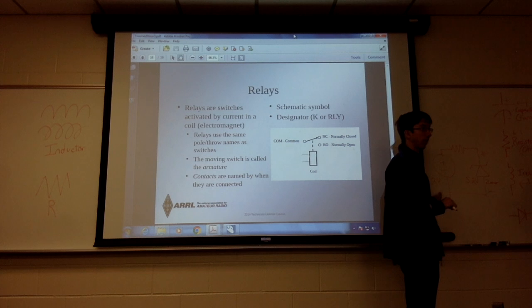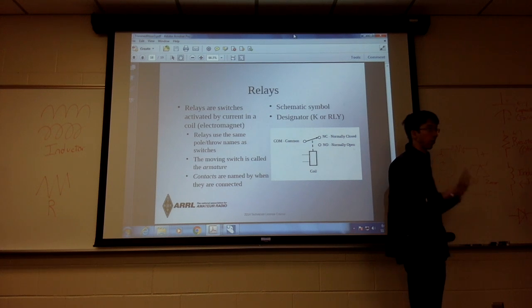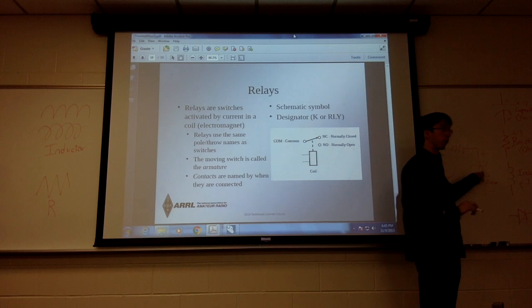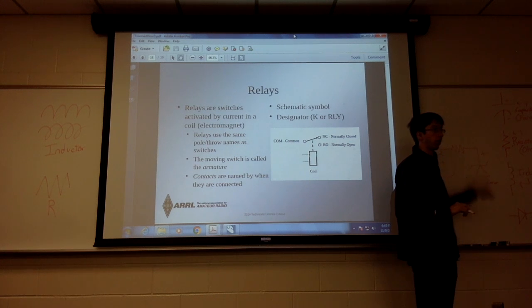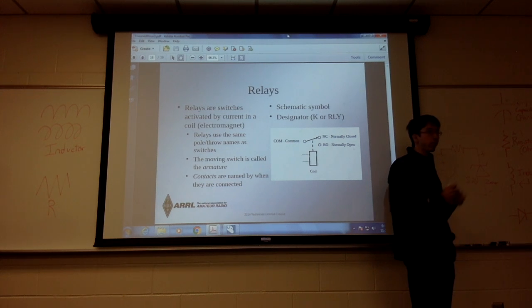If this is 1,000 volts, we'll kill it by other means. As long as this is greater than 5.2 volts, we end up with 5.2 volts across our Zener. That's why it's useful for voltage regulation, because it doesn't matter if that's 12 or 14 or 15 or whatever; so long as it's greater than 5.2, we'll end up with 5.2 on the output.